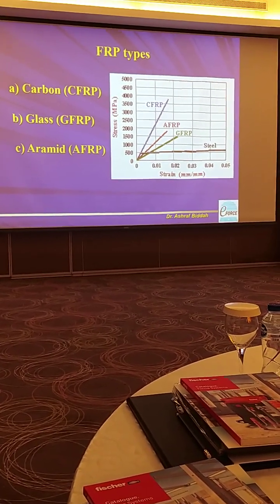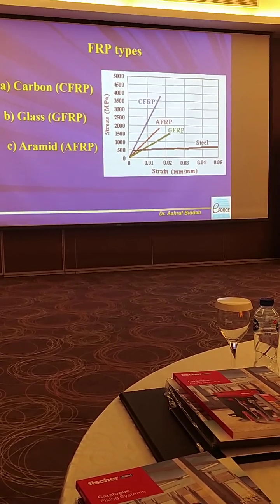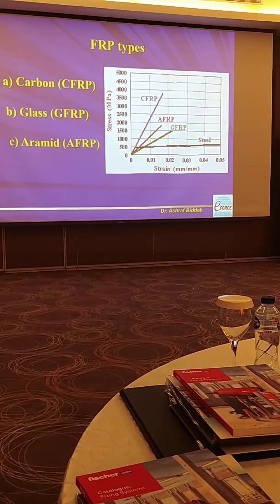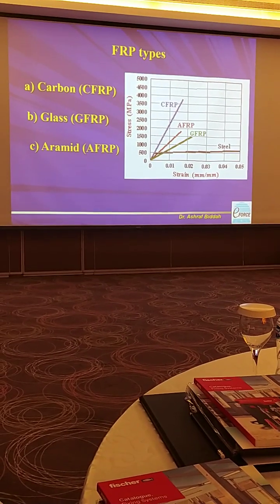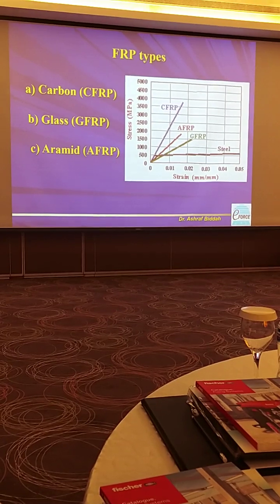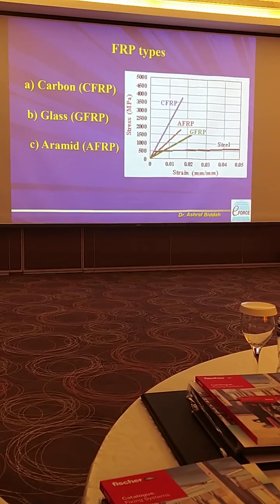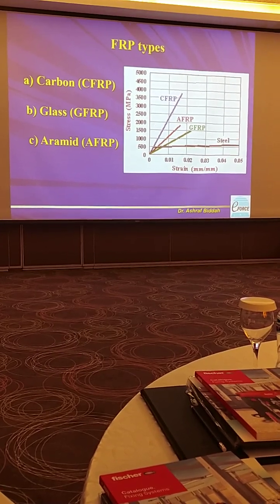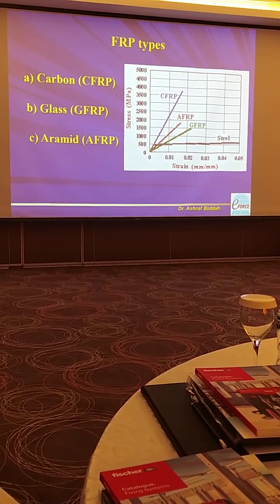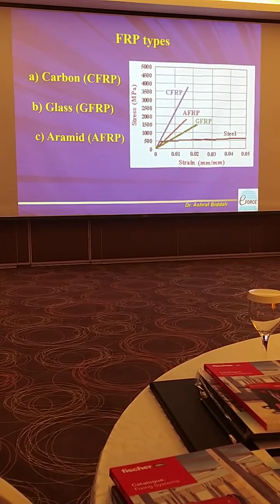But if we talk about carbon fiber, instead of 600, 400 or 460 here, we are talking about 3,000, 3,050, 3,500. We are talking about glass, 1,500. Aramid, around 1,700. Oh my God, that's huge. But we have two issues we need to consider.